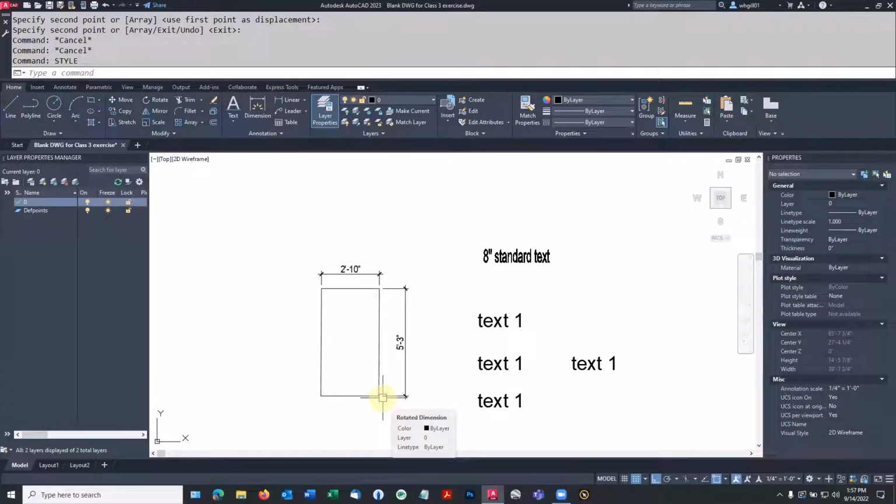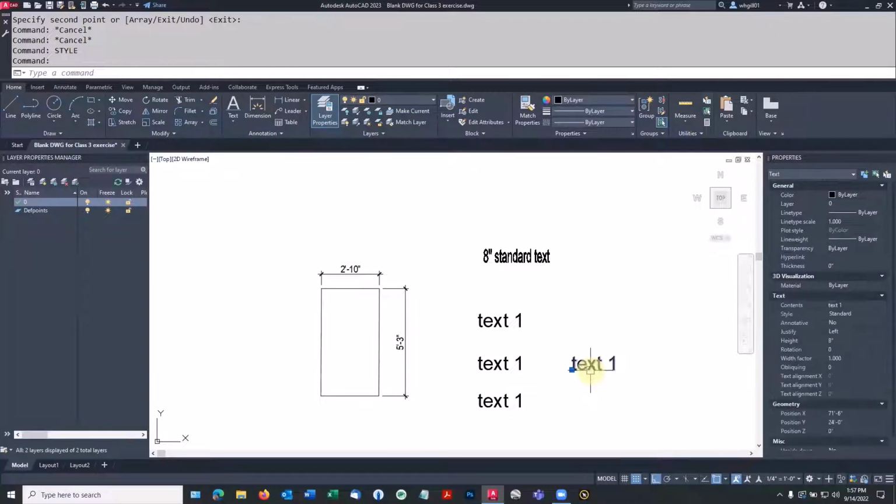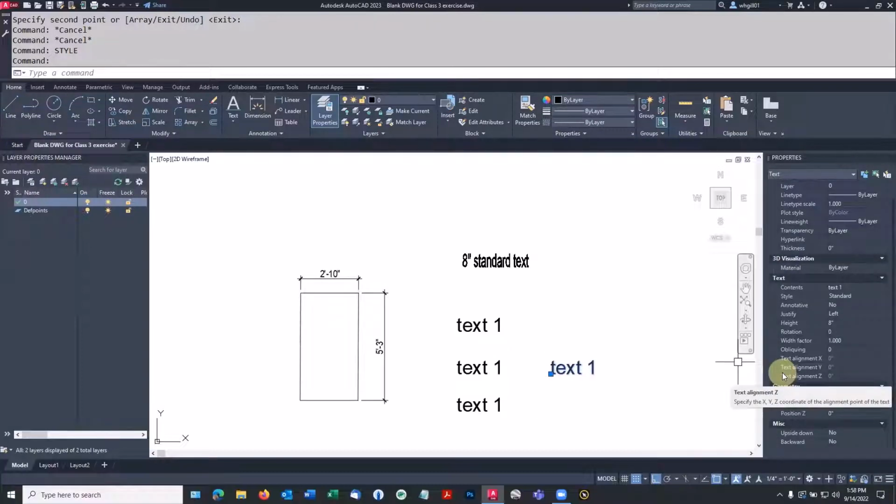I've redefined the style. These belong to that style, so they pick up its attributes. There are a couple of things that we can keep on doing. Anything that the style sets, the individual object can override. So these are all now in the standard text style. This one has been shrunk, although the font updated. And we can change the width factor of individual ones. That might be a case where the word dining room or butler's pantry doesn't fit in the space, so you just need to crank it down, but keep it in the same family and the same height.